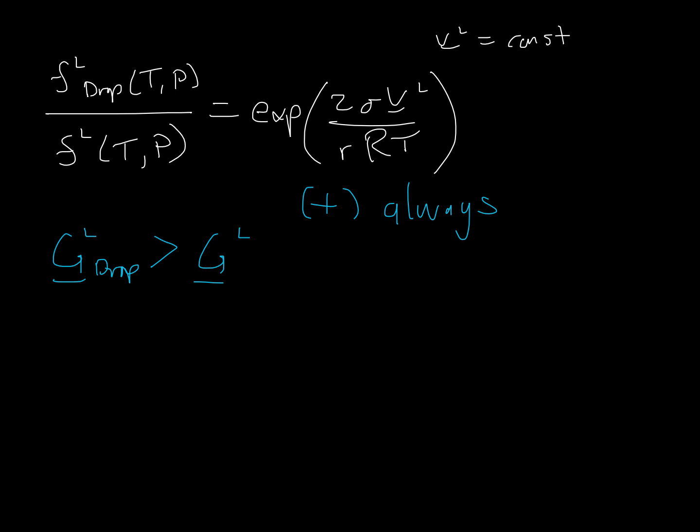So this has a couple of different consequences. One, droplets evaporate faster, or condense faster if you have a bubble inside of a liquid. So let's say, for example, you're designing an engine, and you want to inject gasoline into it. Making small droplets is great because you have a ton of surface area for the volume of fluid that you've injected. That surface area is necessary for the mass transfer process to physically get those liquid molecules into the vapor phase, because they have to diffuse through the gas.